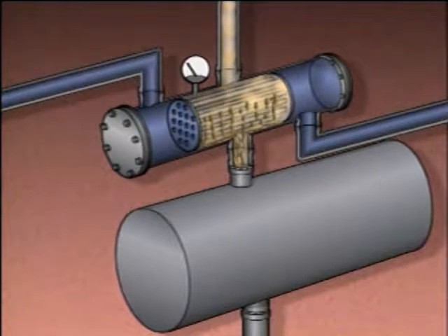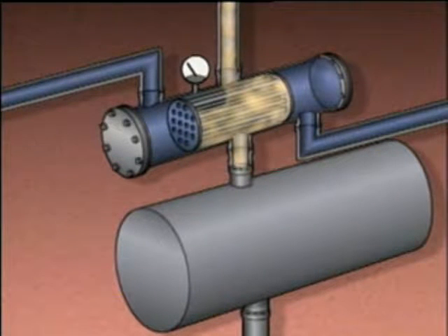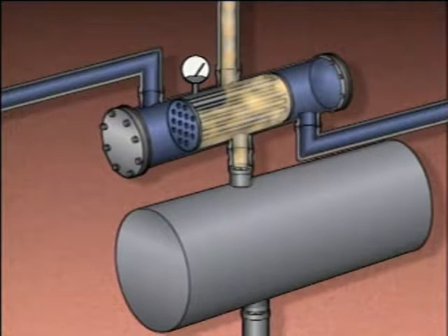When this happens, the gases insulate or blanket the tubes and reduce the amount of heat transferred in the condenser. As a result, less vapor will condense, and the pressure inside the condenser will increase. The increase in pressure may reduce the flow of vapor, or it could stop the flow altogether. As an operator, you may be responsible for the operation of many different types of heat exchangers, including condensers.